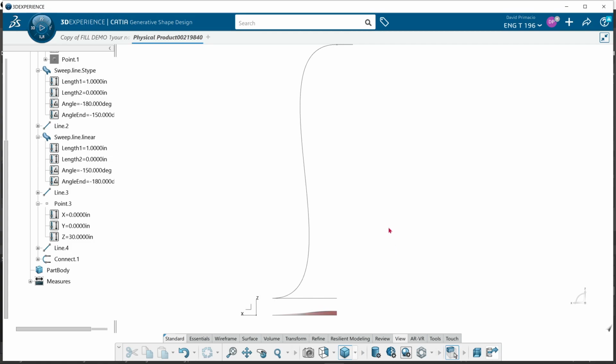So how this has been working is you made a curve, right, before the definition curve and the reference curve. And what it does is it makes perpendicular projections from the reference curve to the definition curve. As soon as this definition curve hits the reference curve more than once, it's not going to work. So, for example,